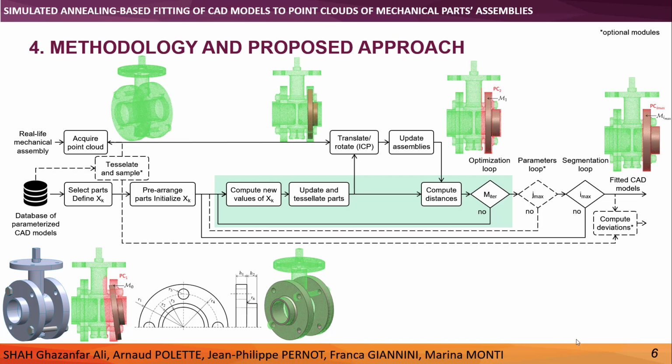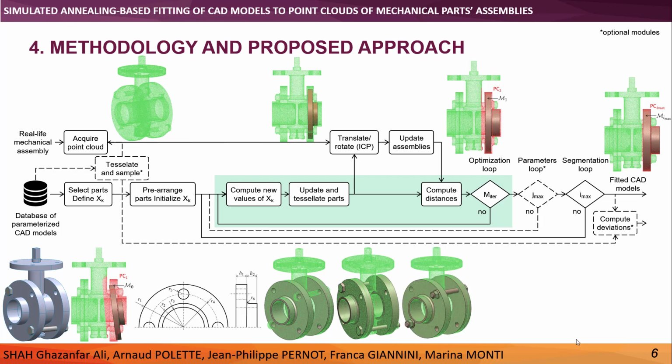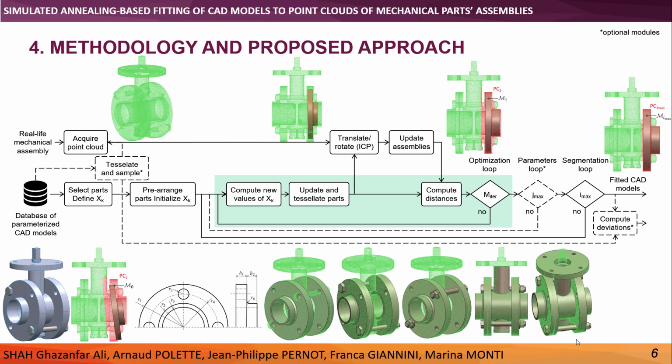So for assembly fitting, first we have fitted these two flanges. Later we have fitted these two bolts. Of course, these bolts also involve some assembly constraints like concentricity between the shank of the bolt and the hole. Also, there is a face coincident constraint between the head of the bolt and the face of the flange, and these two bolts are fitted simultaneously again. Next, we fitted two screws, again involving some assembly constraints, and then the central part and the top plate and bottom plate.